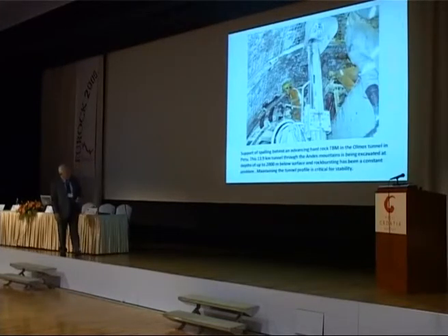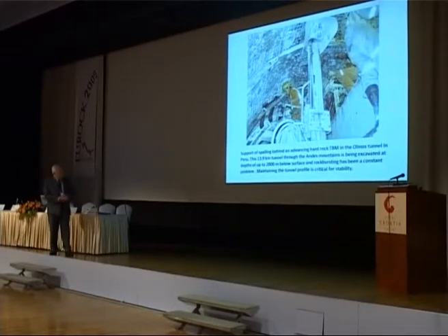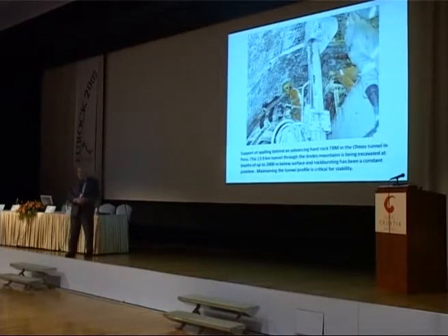This is an interesting tunnel under construction in Peru at the moment, the Olmos Tunnel, 2,000 meters below surface through the Andes, and it's a 13.9 kilometer, 5.3 meter diameter TBM driven tunnel, driven by an open face TBM with constant rock bursting. I'm visiting that tunnel next month.